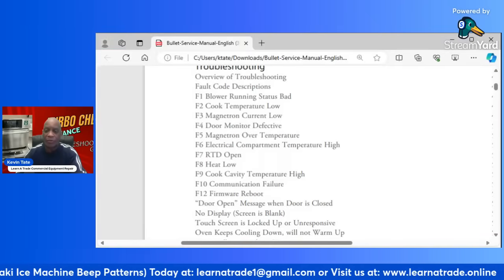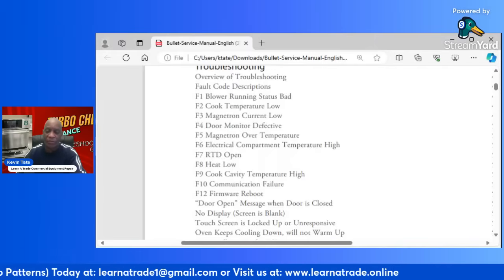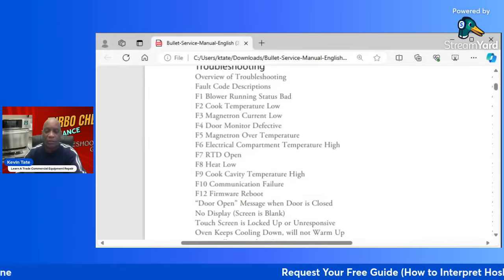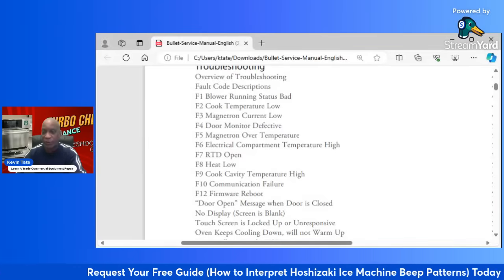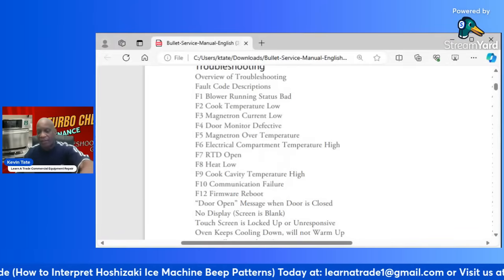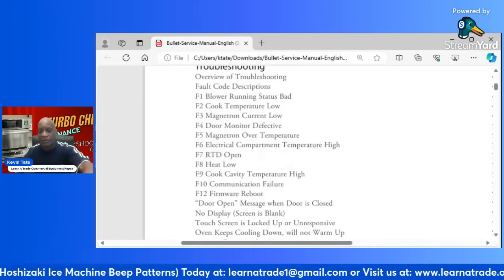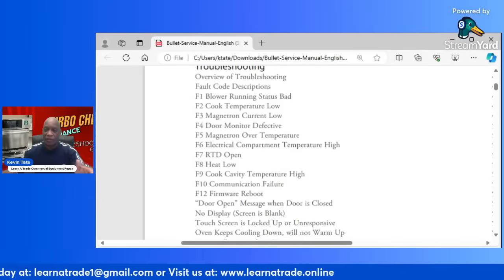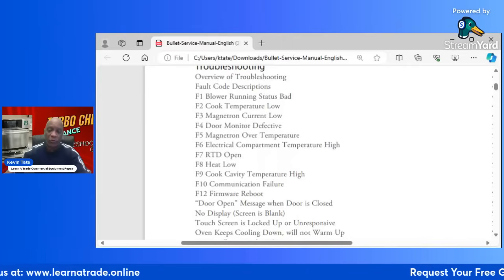But the most important one that I found to be the more common one for the EC temp being high is because the customer hasn't been cleaning the machine, number one, and they haven't been cleaning the air filter, which is in the very back. The air filter slides in and out of two slots right in the fan compartment, where those three fans that we were just talking about are at. That's where that air filter goes over.